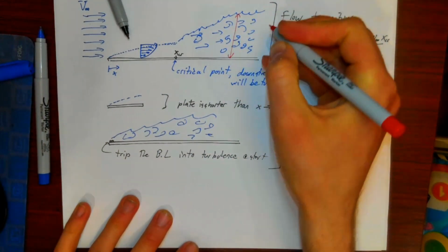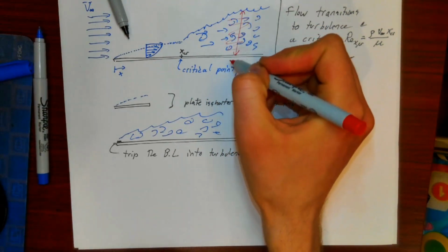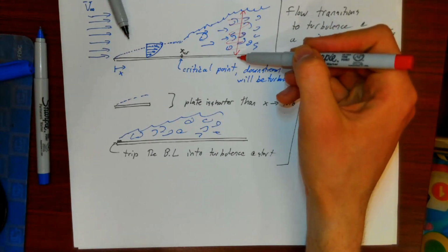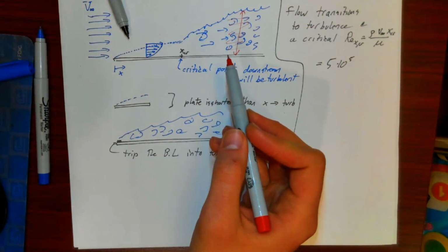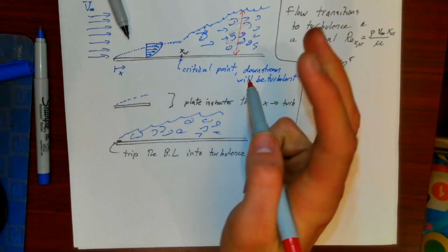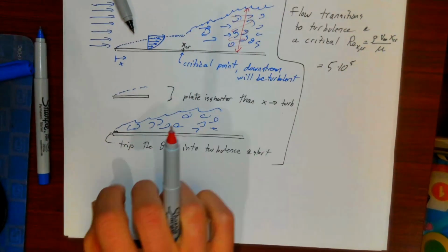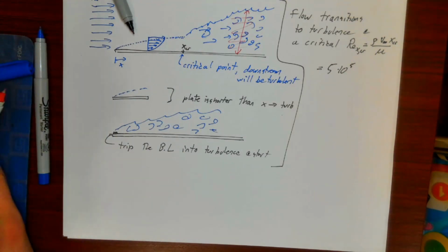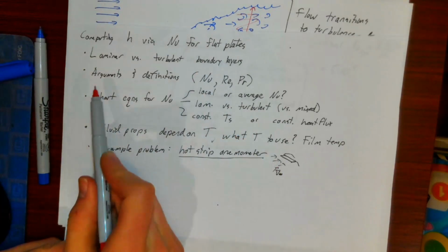They tend to be thicker, but they also tend to be more homogeneous in terms of mixing cold and hot fluids. And it turns out both of these factors impact the heat transfer from the surface. So laminar versus turbulent boundary layers end up being super important towards computing Nusselt numbers and eventually h's, or the heat transfer coefficients associated with this convection. So let's consider this qualitative description of boundary layers when we're talking about the Nusselt number equations for laminar versus turbulent flow.